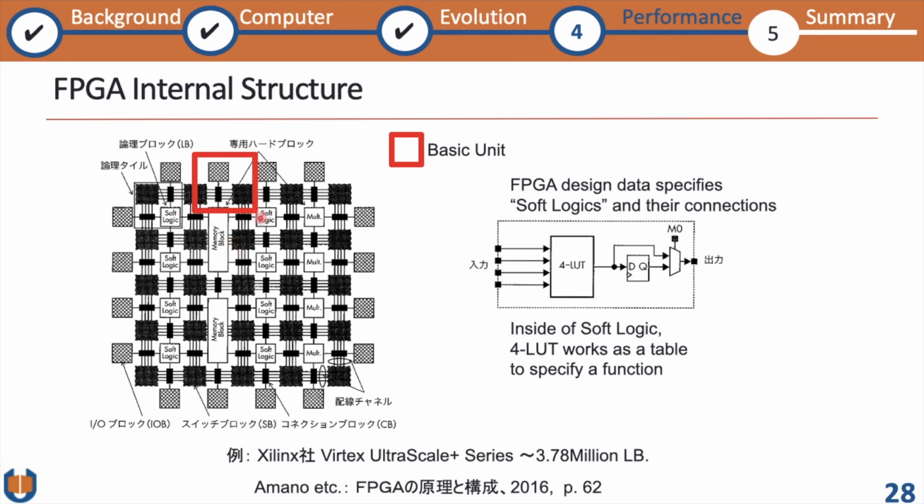This is the internal architecture of an FPGA. There are lots of lookup tables inside. You can design your circuit inside the lookup tables, and each lookup table is connected to the others. There are also some memory blocks and some built-in circuits like multipliers and other things that can be used for any of these lookup tables.